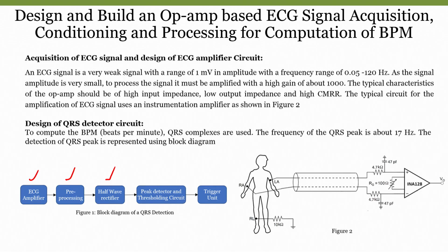So, one step is our rectification, where, using half wave diodes, we will convert our AC signal into pulsating DC, right. The problem with a simple diode is impedance matching. So, that is the reason if you want some gain as well as some kind of impedance matching, rather than having a simple diode, if we go with a diode with an operational amplifier, it will always have a better advantage.